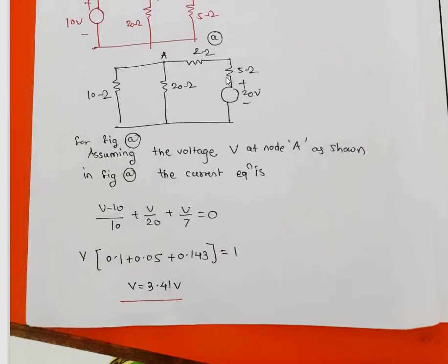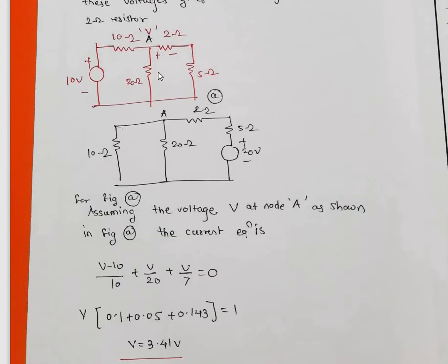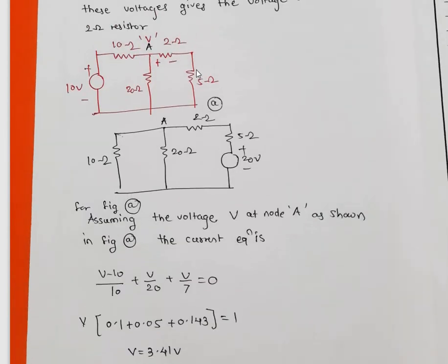So here, we are applying the voltage division rule, not in this circuit, sorry, this circuit. So here it is V potential, and the voltage division rule we will apply. The voltage drop across 2 ohm will be, by the voltage division rule, the same resistor multiplied by the voltage divided by the total resistor, that is 2 plus 5.